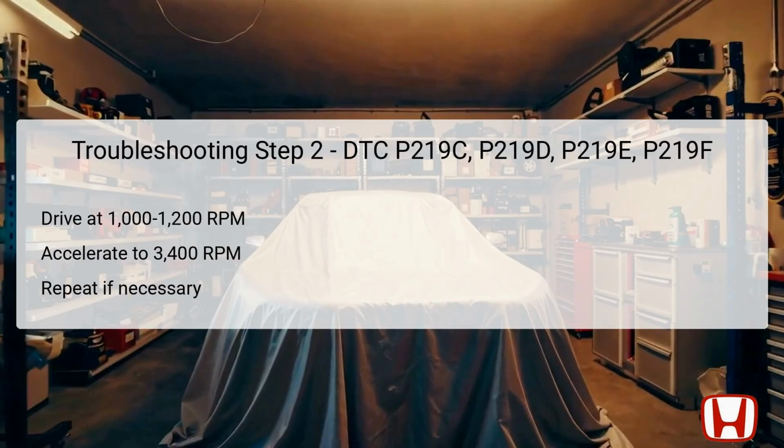In the second troubleshooting step, once the engine is idling quietly, drive the vehicle at a steady RPM between 1,000 to 1,200 RPM. This RPM range is crucial as it replicates typical driving conditions while also putting stress on the engine and management systems. Following this, accelerate smoothly up to 3,400 RPM over a period of about 10 to 15 seconds while monitoring the engine's performance closely.